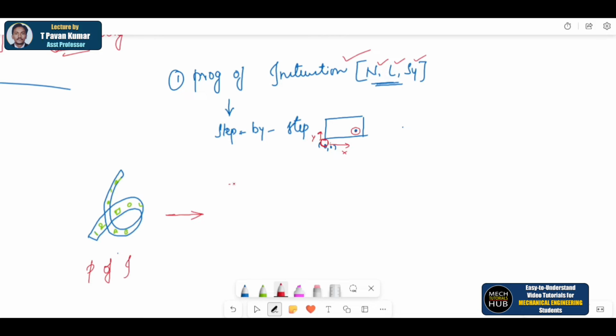Then there will be a control unit. This is how the control unit is going to be. It is a simple sketch, try to understand. There are two rollers on which the tape will be rolled and the information will be read and interpreted. Whatever the tape is prepared with, symbols, numbers and letters, will be passed on to the controller. This we call the controller unit or control unit. The information is read and interpreted, and that information is passed on to the machine tool.